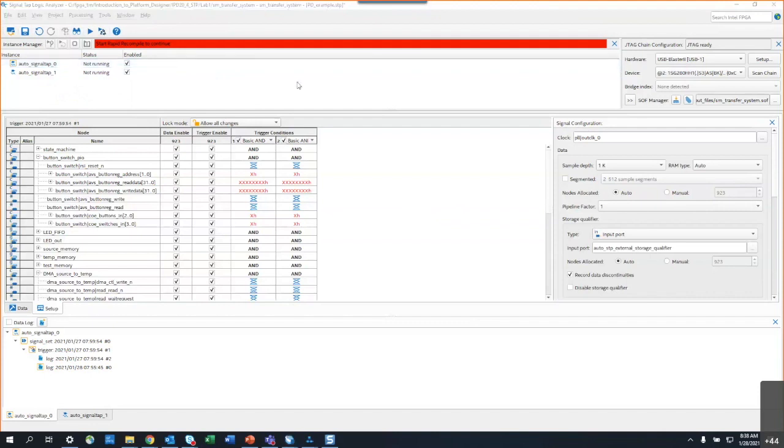So in the Standard Edition of Signal Tap, you can view that information. You can see how much logic, and as you make changes to your trigger conditions or the buffer, it updates on the fly to show you an estimation of resource usage. I thought that was in here, but it is not, so maybe they have not implemented it in Pro Edition yet for some reason. But that is the main way to know.